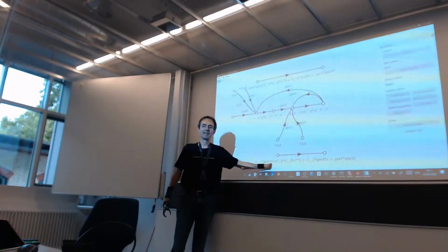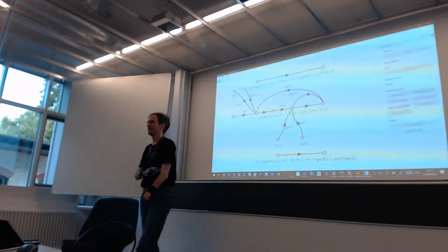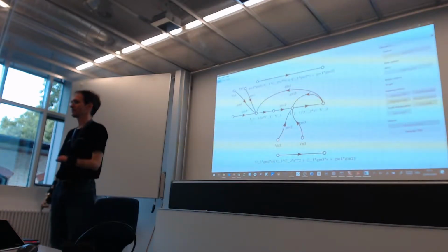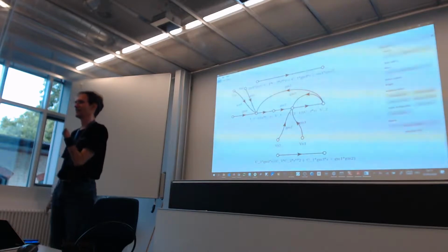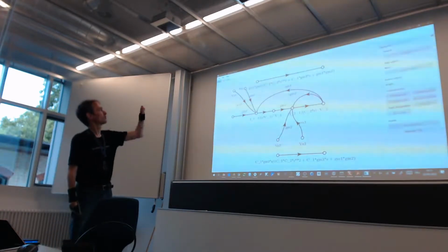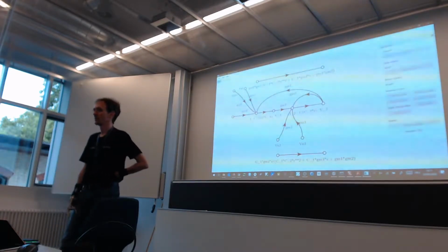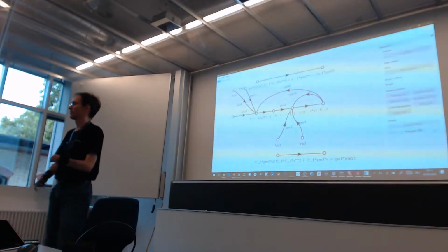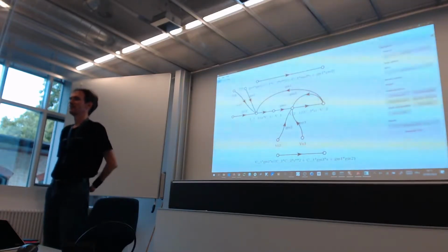Here now suddenly I have an S in the numerator. So this is a bandpass filter. So fundamentally you see that the noise of two of the transconductors is low-pass filtered, and the noise of the other two transconductors is bandpass filtered.